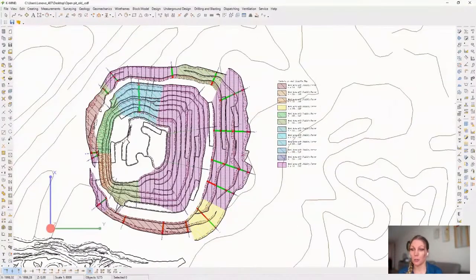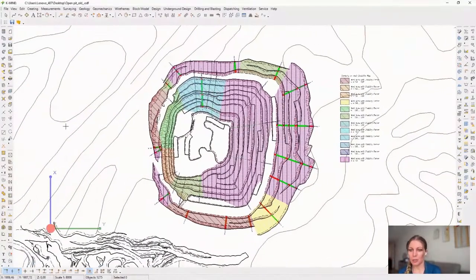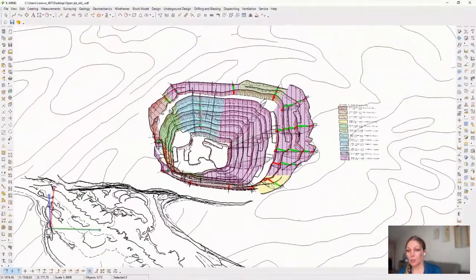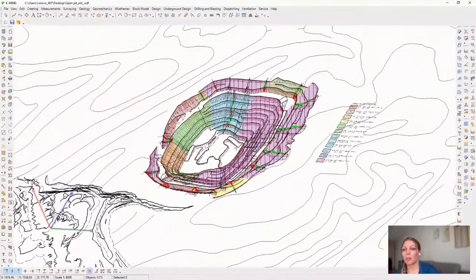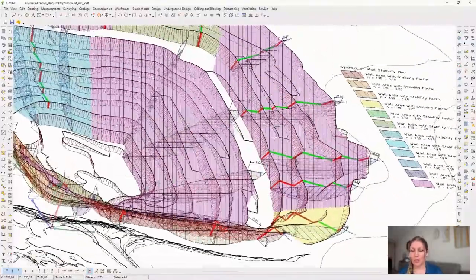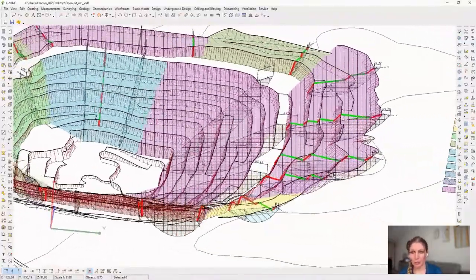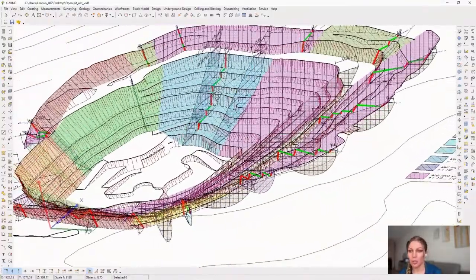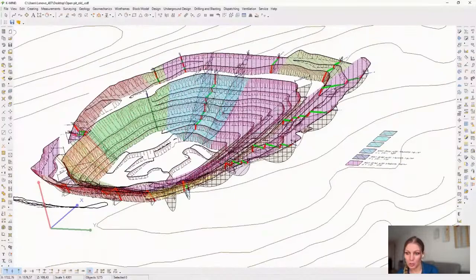Additionally, we can utilize the filter that takes into account seismicity by enabling the appropriate flag. In addition to the safety factor, we can also calculate the slope angle for a given stability factor. This information is incredibly valuable because it allows us to design and implement slope stabilization measures that are effective and efficient.